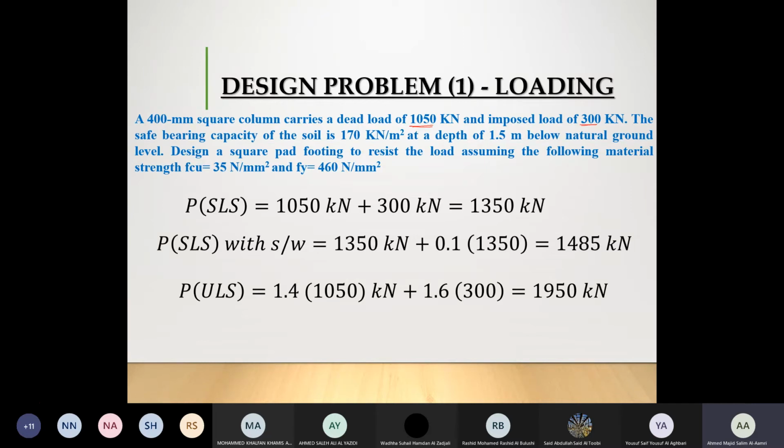At the beginning, we kept the foundation in the soil. It will not bend. Whenever we start loading the column, you will see that this loading is trying to push down, and the capacity of the soil is trying to push up, and because of that, this element is trying to bend upward. So once again, when it comes to calculation of bending moment, we don't take the self-weight into account, because the foundation is kept in the soil. It will not bend.